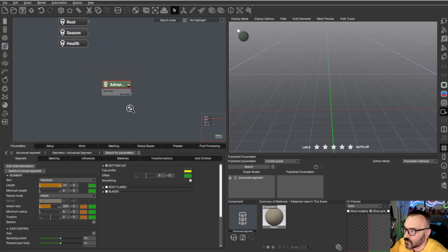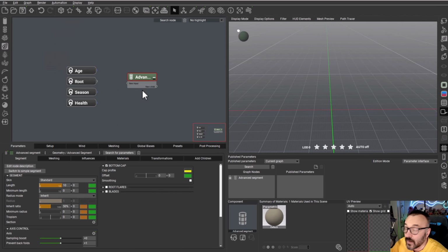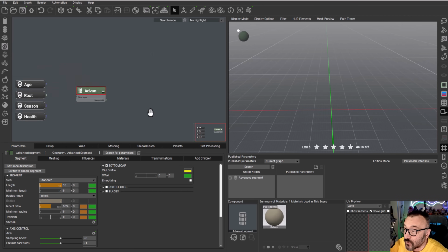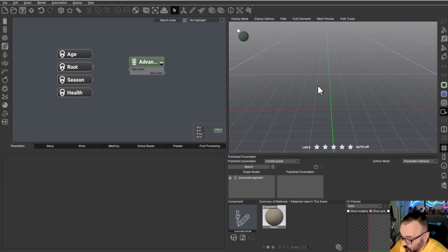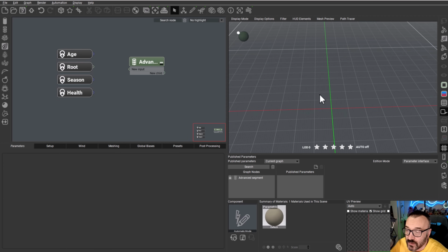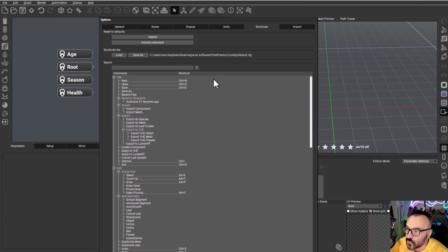And okay, let's zoom out, because we kind of don't have it. There you go. Okay, let you know one thing. Navigation could be a little bit confusing, primarily with a mouse, because you need to click the right mouse button and drag around. Middle mouse is zoom. And right here, for example, you need to hold the Alt key and use it with the Alt key. So some key bindings are different from maybe your applications, but you can always change this if you go to File, Options, and inside Options, you go to Shortcut, and right here you can change them if you want.